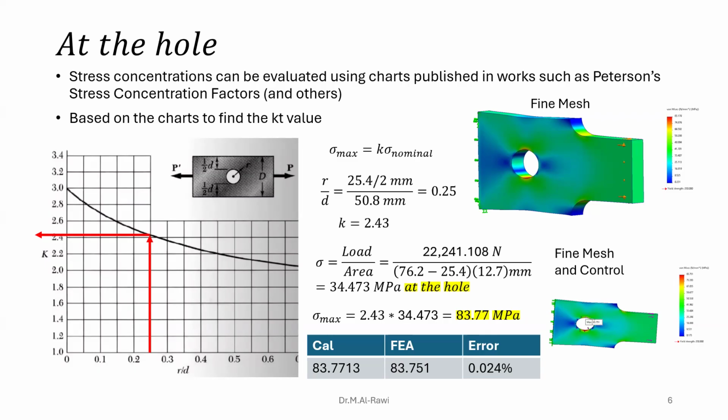So control mesh is very interesting. You just focus on the area where it's high stress. It's saving my time for computations. I don't need to make it all fine. So I'm just showing you, if it's only fine, it's 83.17.